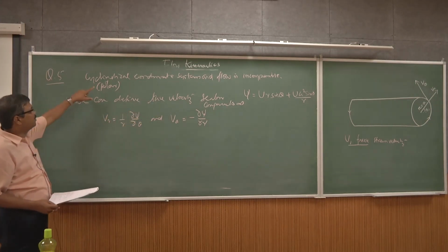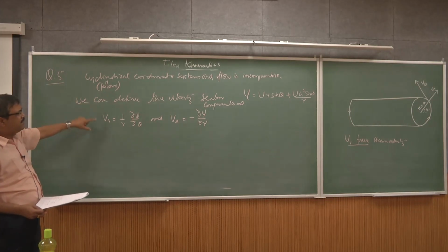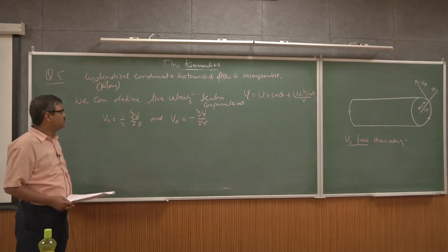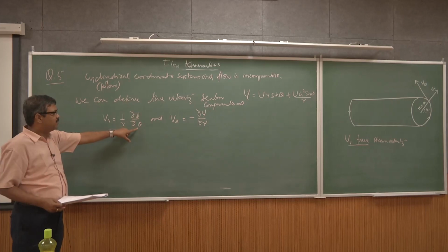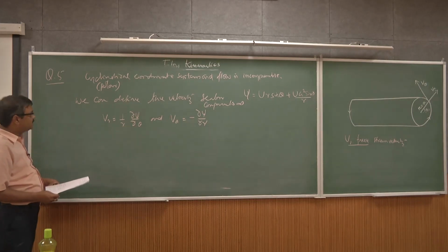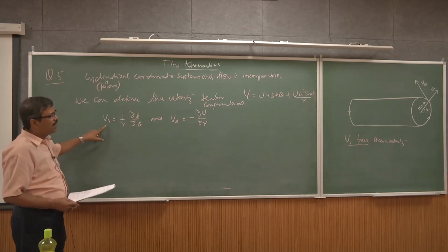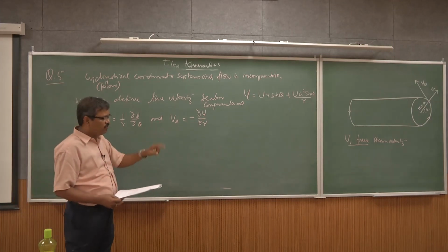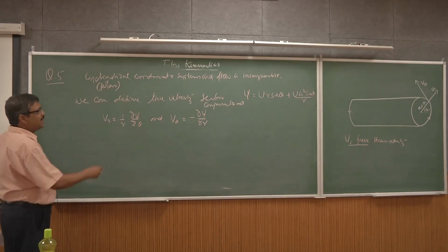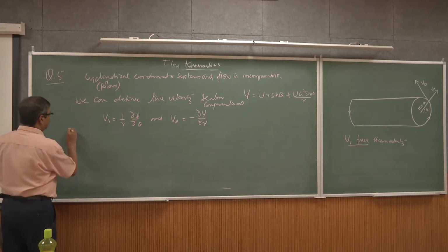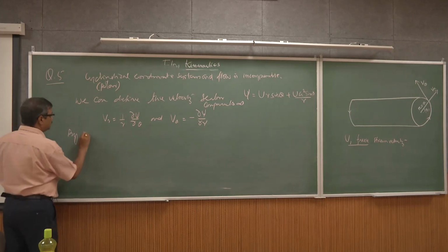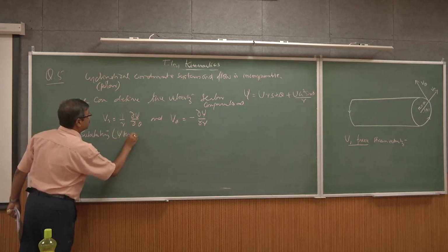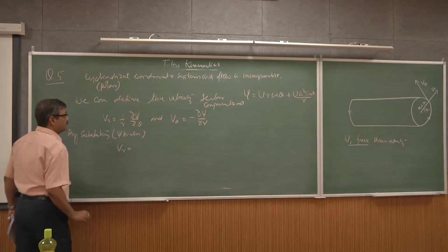and the stream functions for a polar coordinate system, which is the same way as we do it otherwise, but just note the one 1/r component that comes in when you take the partial derivative with respect to theta. So, as this problem is given to us, we just have to find out whether V_r, the radial velocity component, is equal to 0. So, it is a very easy thing. Now, let us compute it by substituting the stream function.